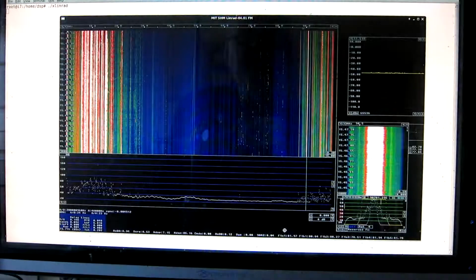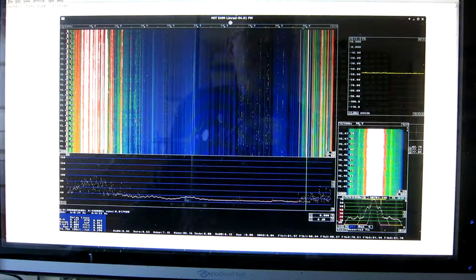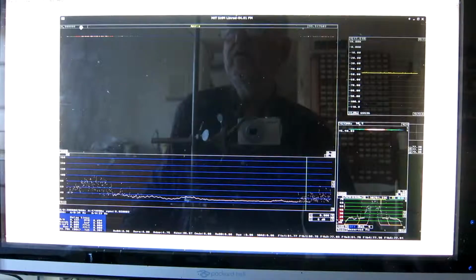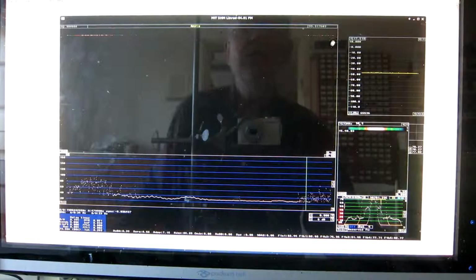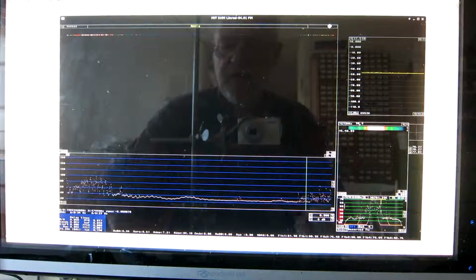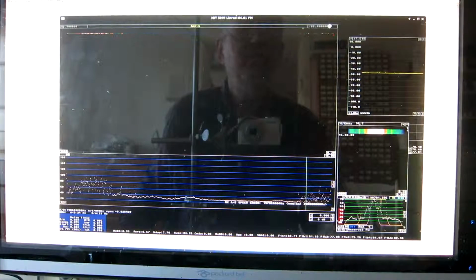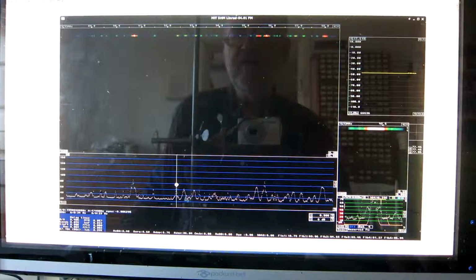And you can see Linrad runs beautifully, there are no glitches, no error messages. I can zoom into the FM band, I click here and feed the lower frequency, 88 megahertz, up to 100 megahertz. Enter and then click on apply. And here we have the FM band and I can listen to the different stations.